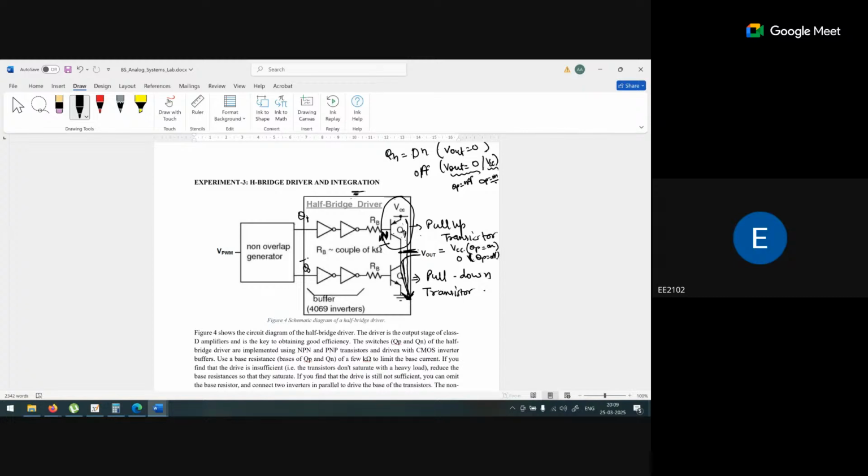Like we are saying that we are using a two-way H bridge. One is the V out from here, and the second V out from here. So when it is VCC on one side and 0 on the other, what is the direction of the VCC with respect to 0? We are saying that my motor will be rotating in this direction. In the second case, if it is VCC and VCC, we are saying that it is a clockwise direction.